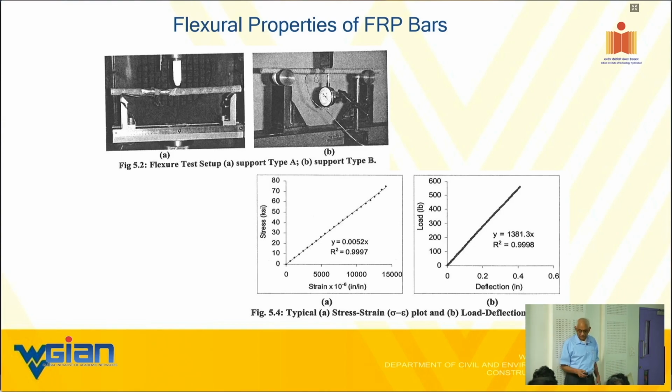Okay. One more thing, sir. When we apply cyclic loading on an FRP frame, for example, in the case of the steel reinforced member, there is formation of plastic hinges, but we don't have that in FRP. Correct. So it means that we can't use that in seismic zones? Well, again, we don't have enough data to speak about that like the way you are saying.